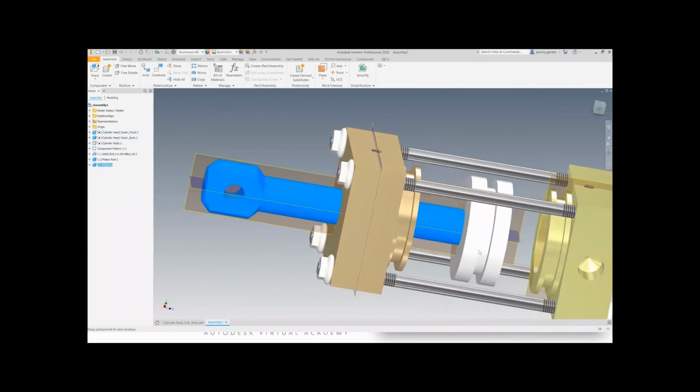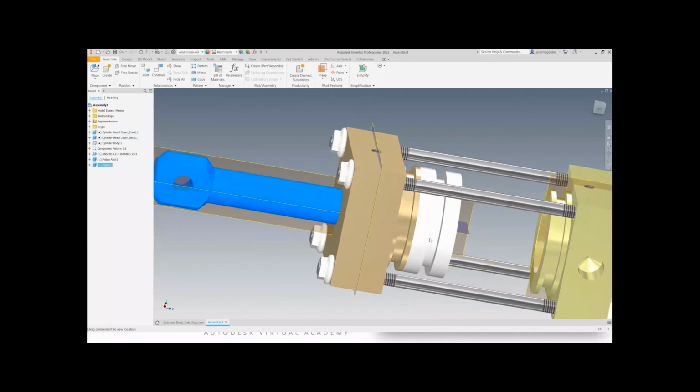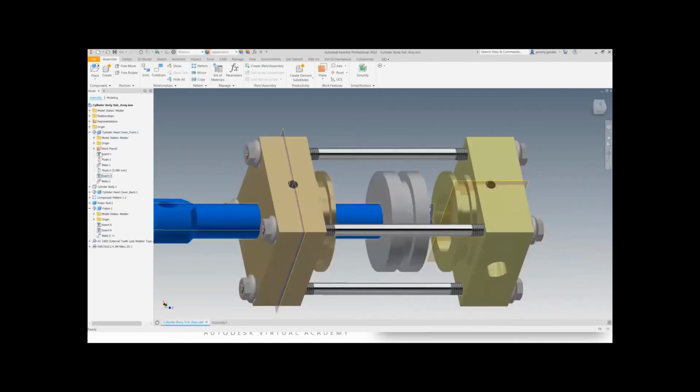And then for this part, in its subassembly, it'll always have this ability to move. But once you put this subassembly into another assembly, it'll lose its ability to have that movement unless you turn the parts into contact sets. I'll show you that. So make sure I'm going to grab all the right parts to do that. Yes, piston and that one.